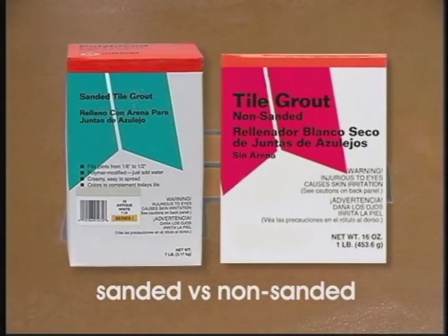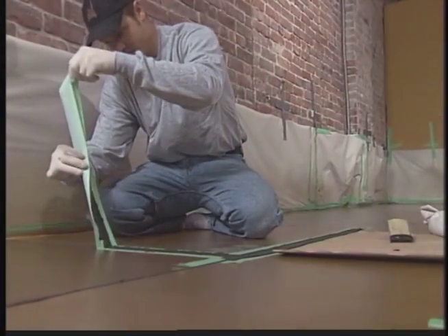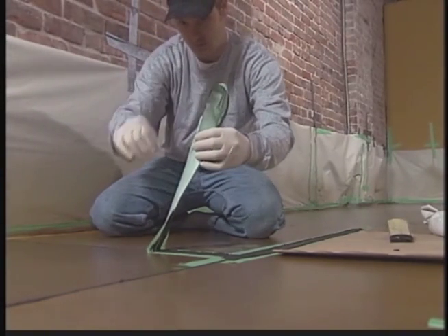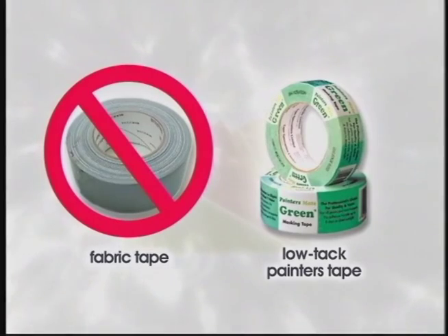Some sealants are breathable, and grout pigment may absorb into the surface, causing discoloration. A very low-tack fresh paint tape will prevent color from bleeding onto the surface, and when carefully removed, will not peel or lift sealants. Never use a strong adhesive tape.